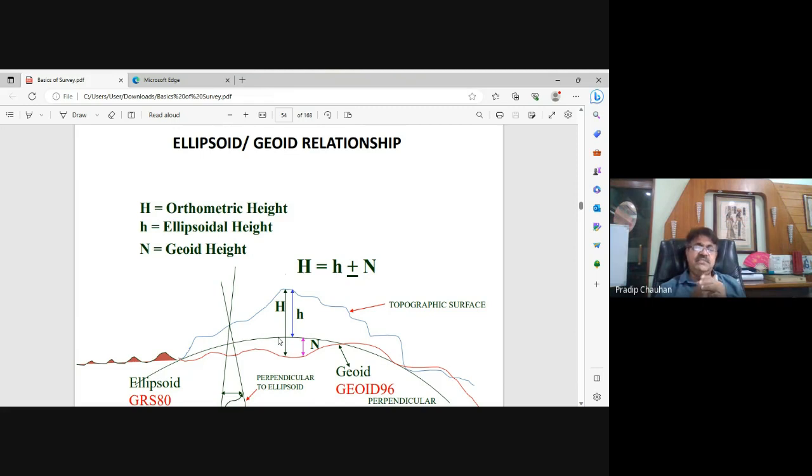So for example, if it is 3 times, in that case about 200 kilometers, and your deviation is 40 meters. So 40 meters divided by 200 kilometers. So the ratio is about 1:5,000. Let me convert that. So it's 1:5,000.